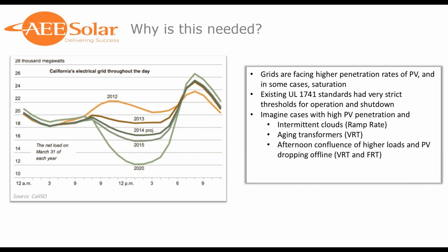Either more generation is going to be taken offline, which is usually what happens behind the scenes. But in the event the utility is not able to get ahead of that, voltage and frequency are going to rise. They're going to rise to the point where the inverters are no longer seeing a qualified grid, and then they're going to start dropping offline as the voltage and frequency come back in spec.